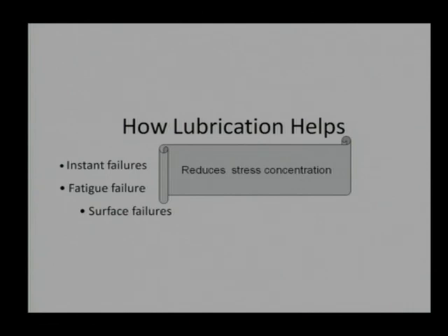The question comes, how does lubrication really help? It was mentioned earlier that it reduces friction and reduces wear, but in addition to that, there are a couple of more advantages of lubrication. We said many times it reduces the failure possibility due to a sudden change in load, sudden change in lubrication condition, or sudden change in misalignment. If there is some lubricant which is stuck to the surface, it will work satisfactorily for a fraction of a second or transient time.